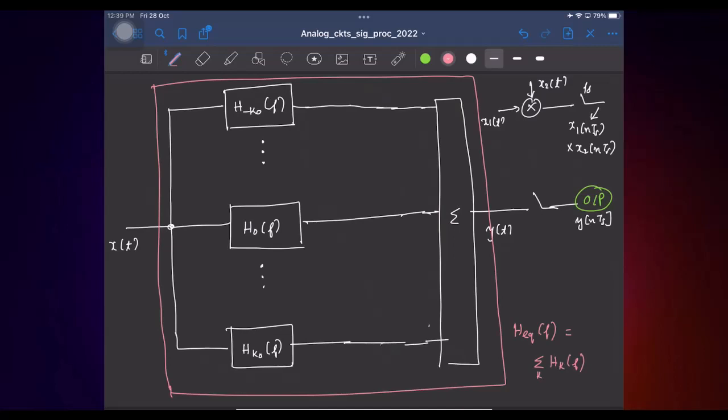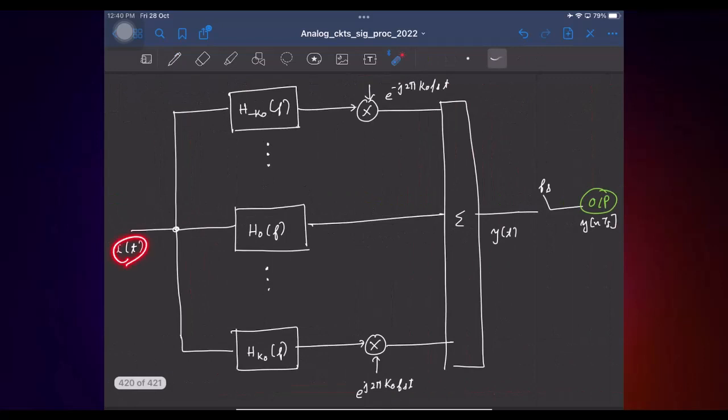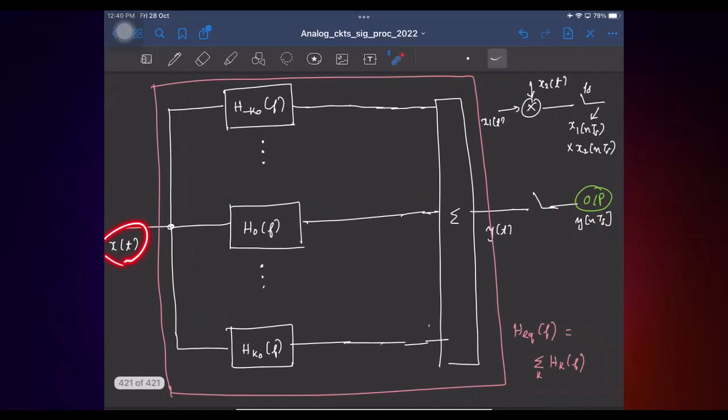Okay. So what we find is, if I take a signal, feed it to an LPTV network, and I take the output of the LPTV network and I sample it, I can get the same samples by giving this input to an equivalent LTI filter, whose output is also sampled at the same time instance. Is that point clear?